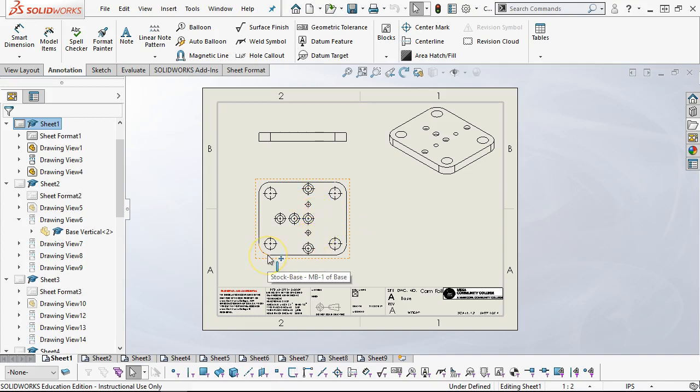So, our process is to apply the dimensions, and then after we've picked out those basic dimensions, we pick out some datums. So you're always going to fall back on your form tolerances before we go up to positional, before we go to location, before we go to profile. And when we get to the cylindrical parts here, we haven't really covered anything that cylindrical, so I want to take the shaft and at least apply that one.